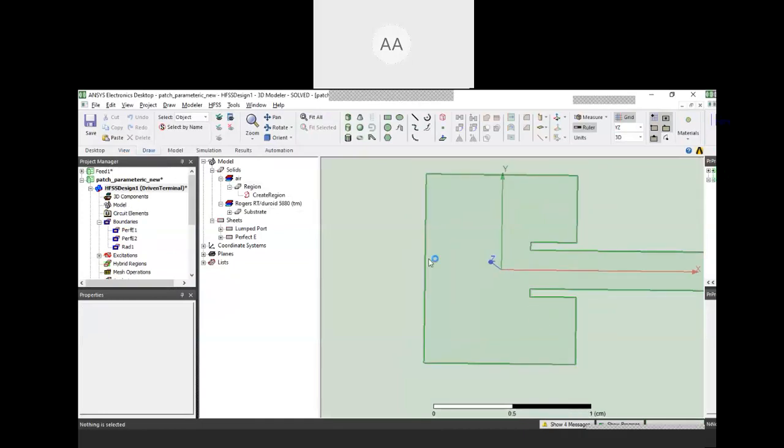Now what has happened is, here on the left hand side, the voltage is maximum, and on this hand the voltage is minimum. At center the voltage is 0. So here it's plus V, 0, and minus V. And the current is 0 at this end, and the current is 0 at this end, and the current is maximum at the center. So based on that, you have to calculate the impedances.